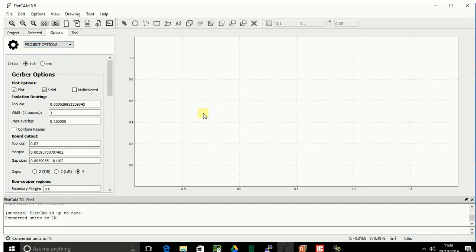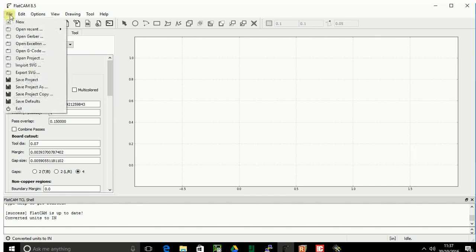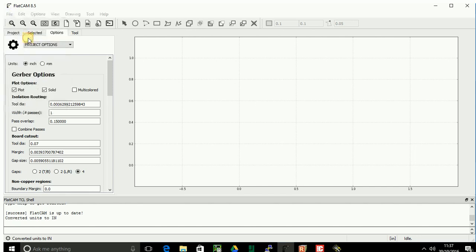when we load the Gerber file and the drill file, if you select the unit in millimeters and you load the files, you see there is an offset between the Gerber file and the drill file. So we load up all the files in inches, then we change to millimeters, and this one seems to do the trick. We load up the files that we are interested in.